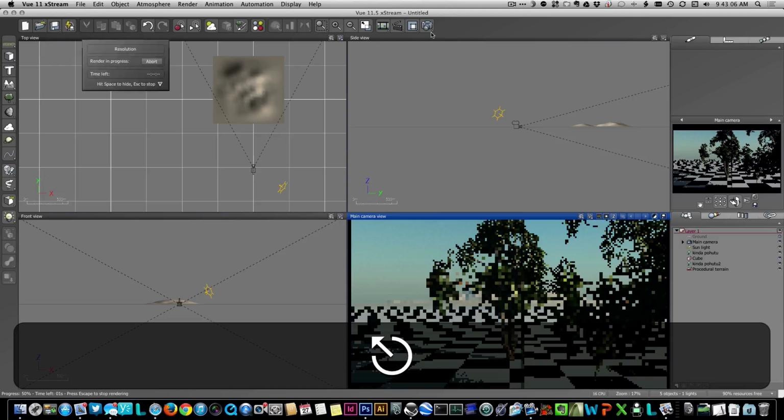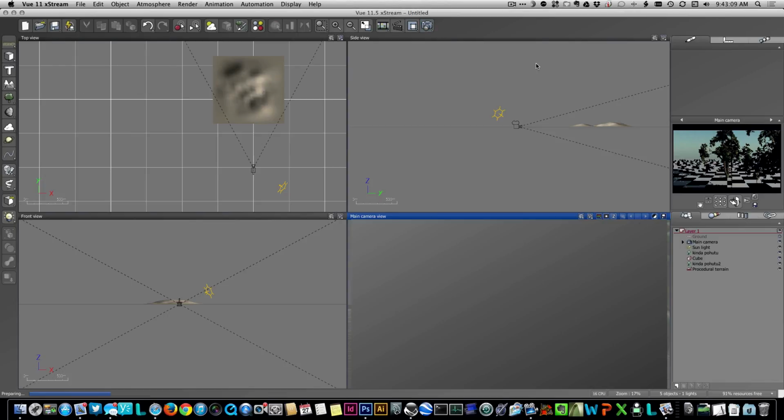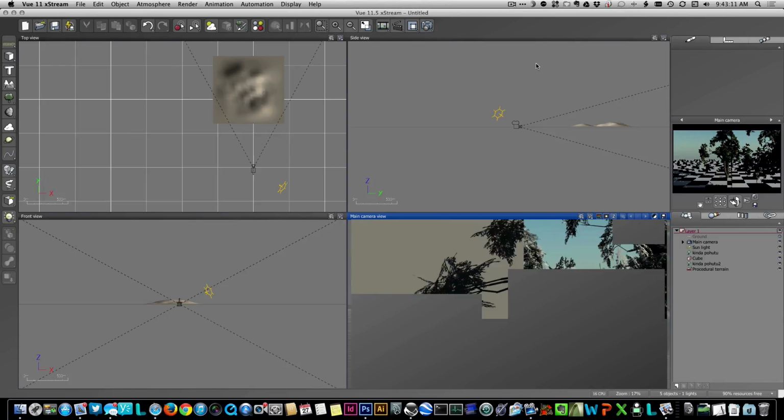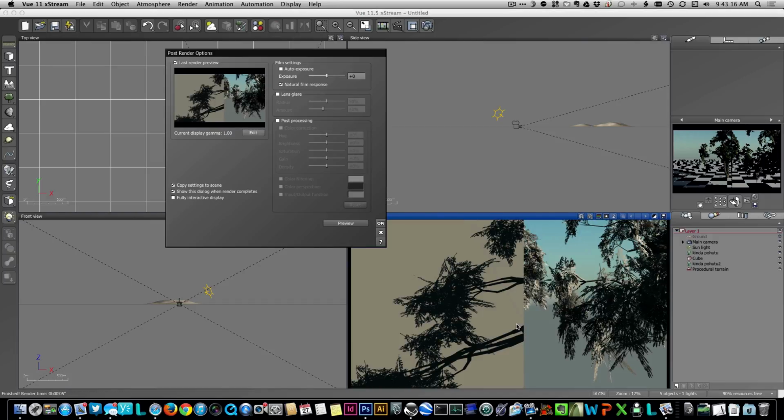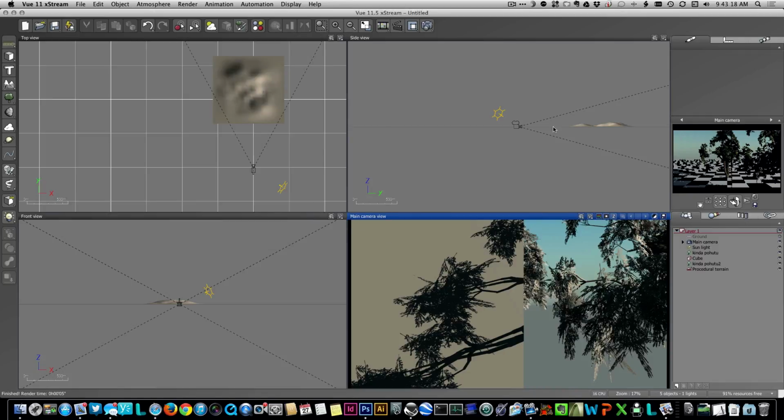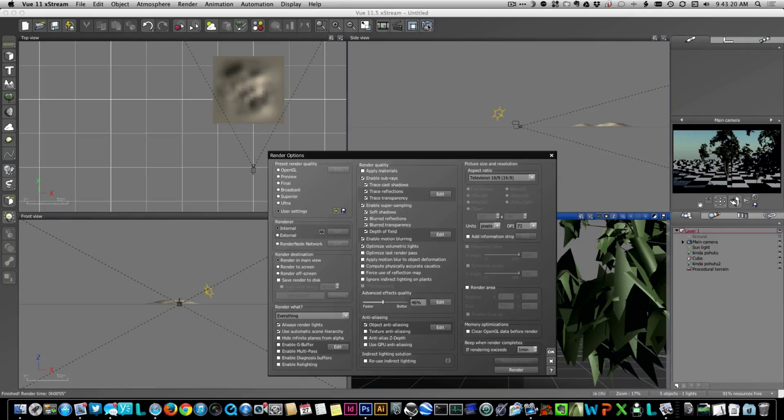Oh man, sorry. You can just turn the materials off and everything turns white. Pretty cool, eh? Still obeys the alpha channels. But you don't actually have to remove any textures. We've got shadows, reflections, transparency. There's a few settings in here on how accurate these are, and we're going to actually have a look at this. But what we're interested in is this depth of field, okay? And there is a couple of options in here.